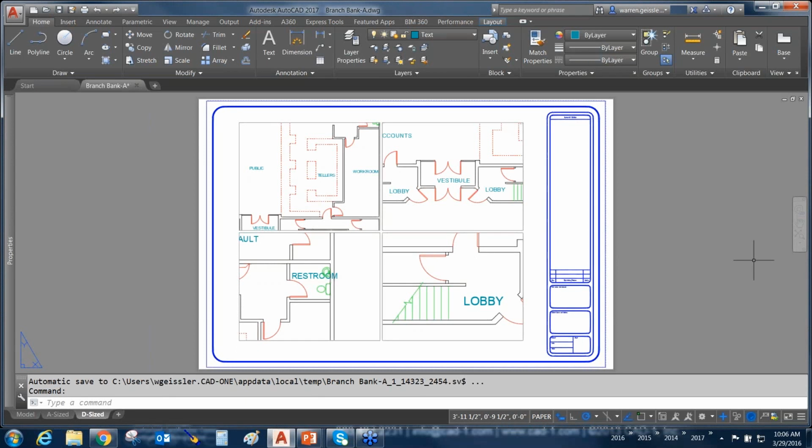So what are we here to talk about today? Well, we're here to talk about AutoCAD annotation scaling. Hopefully everybody who's using AutoCAD knows what AutoCAD annotation is. Now, AutoCAD annotation can take on a lot of different meanings, and annotation is basically text, dimensions, hatch patterns, line types, and even to some extent blocks can be considered annotation. Symbols representing things like switches, electrical outlets, manholes, things that don't necessarily represent a real-world object in real-world units, but they do represent real-world objects, just as symbology.